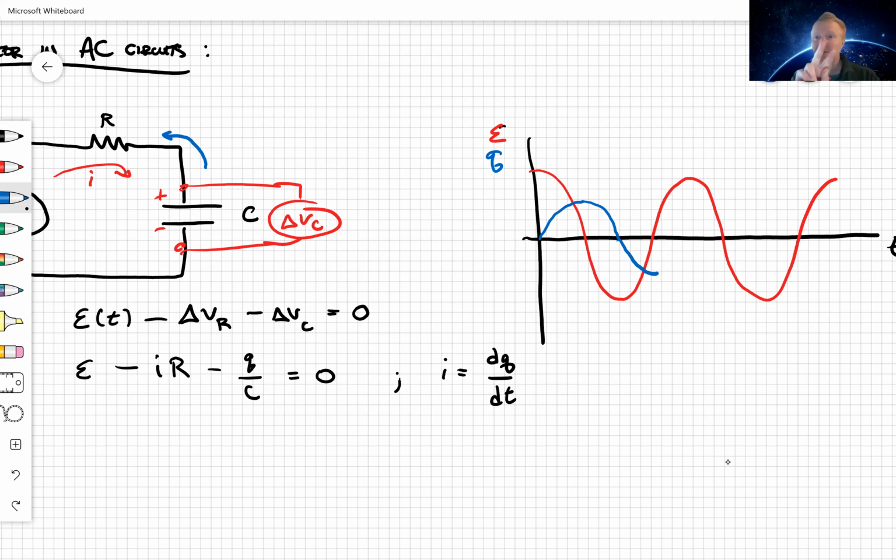And then the voltage flips again. And then you can see, okay, yeah, about like that. Well, that was a little bit short, but you see, these are not in phase anymore. So the voltage across the capacitor and the voltage across the source are out of phase. This is very difficult to comprehend sometimes, okay? Which is why we have our phasor diagrams. Let's do this as a phasor diagram because they're lovely.